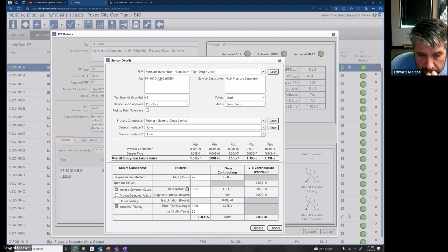Because I don't see the difference, at least here in the calculation, whether I am in a 2 out of 3, I have one of the items which is detected failure, but I do not stop the plant, and then I go into degradation mode. So what should I put there? No, the time to detect is for a single component.